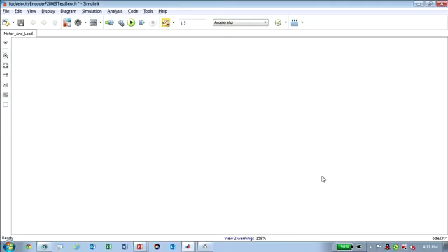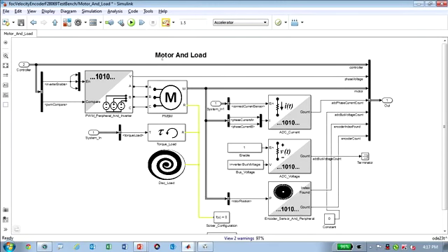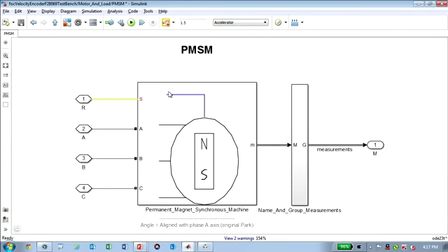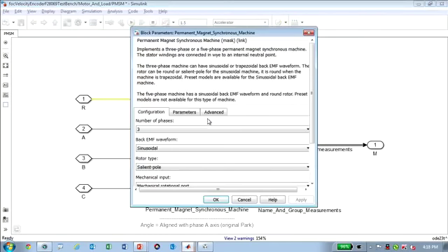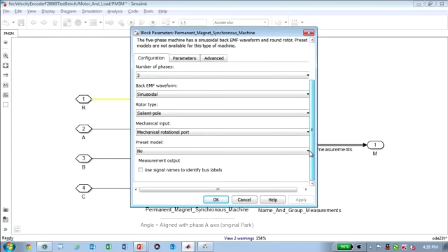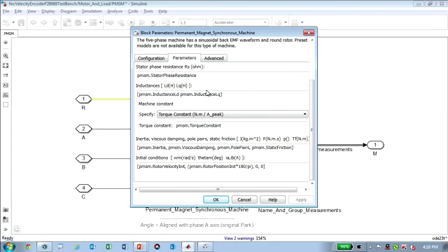Just to give you an idea what's inside of this mathematical model, there's a model of the three-phase motor. There's a PMSM. This is from the product SimPower Systems. It's basically a DQ model. And it's parameterized by a bunch of variables, which means that we can have data and configure the model to map the different hardware that we have in front of us, or we can run different Monte Carlo tests and do different robustness analysis on it.